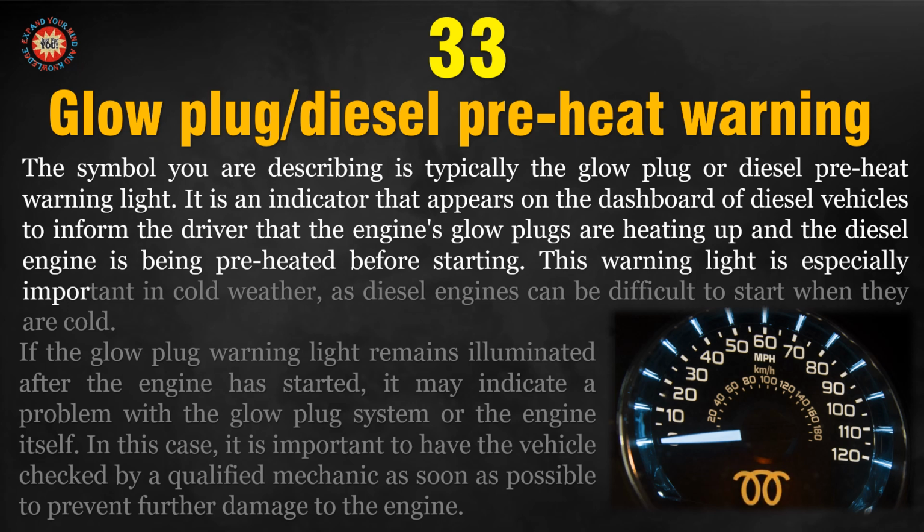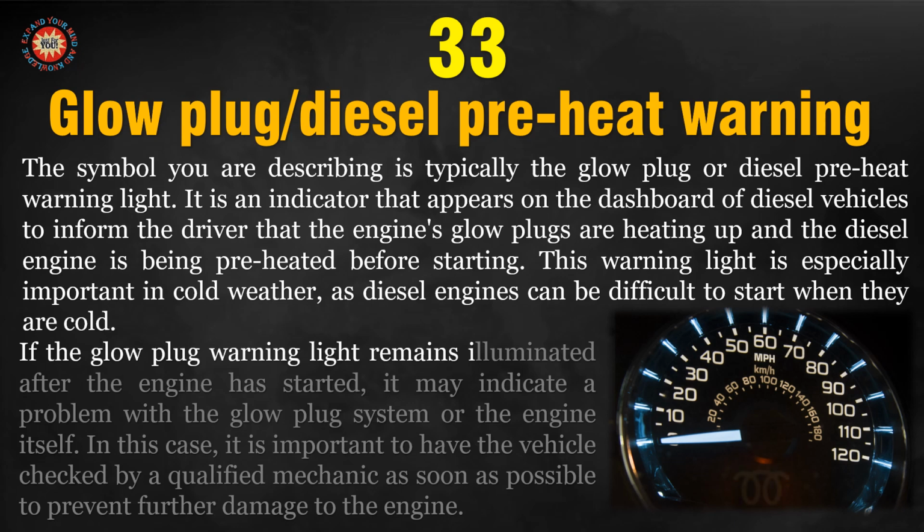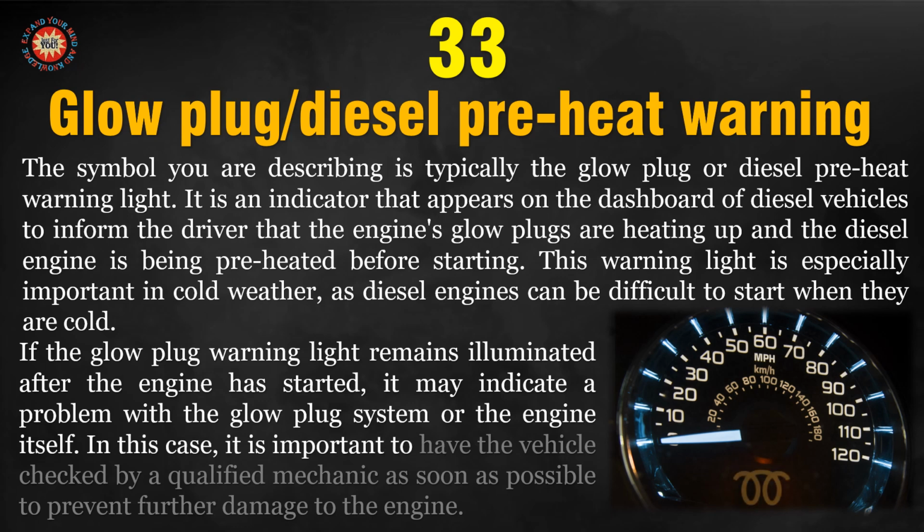This warning light is especially important in cold weather, as diesel engines can be difficult to start when they are cold. If the glow plug warning light remains illuminated after the engine has started, it may indicate a problem with the glow plug system or the engine itself. In this case, it is important to have the vehicle checked by a qualified mechanic as soon as possible to prevent further damage to the engine.